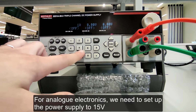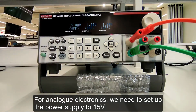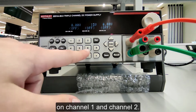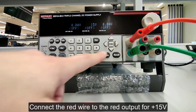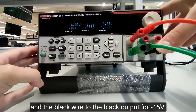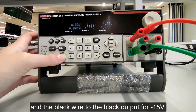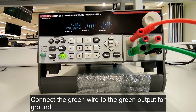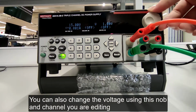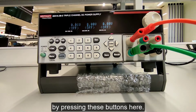For analog electronics, we need to set up the power supply to 15 volts on channel 1 and channel 2. Connect the red wire to the red output for +15 volts and the black wire to the black output for -15 volts. Connect the green wire to the green output for ground. You can also change the voltage using this knob and change the channel you're editing by pressing these buttons here.